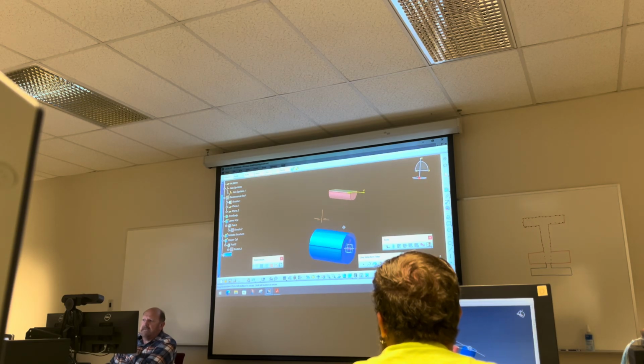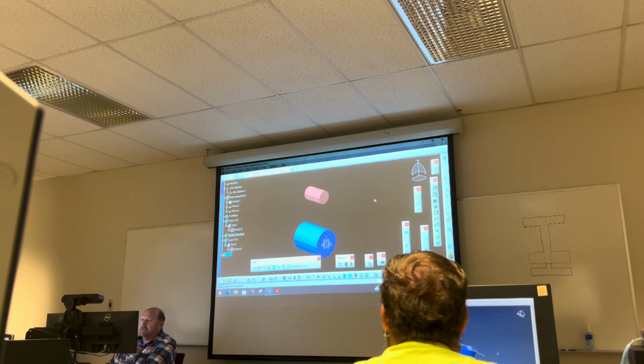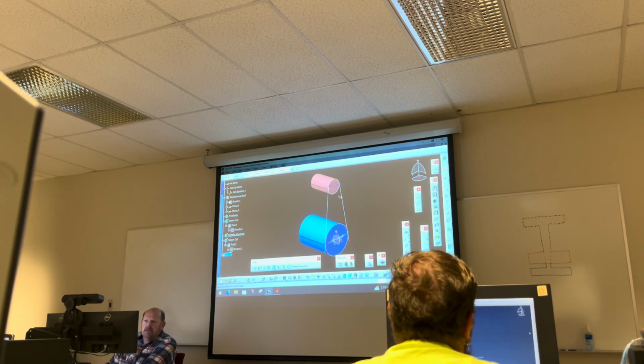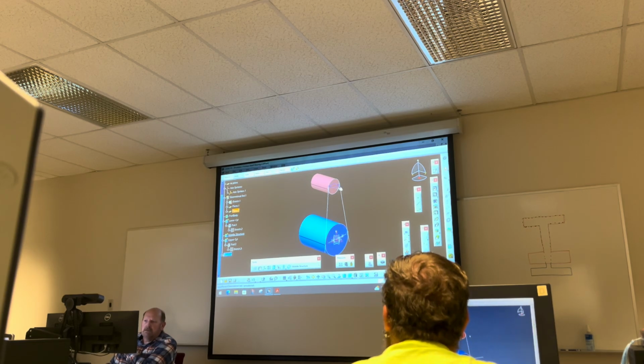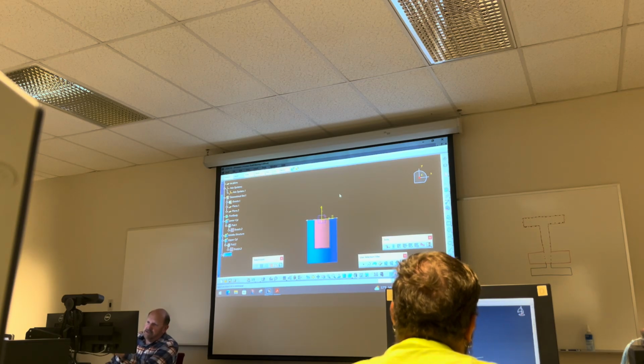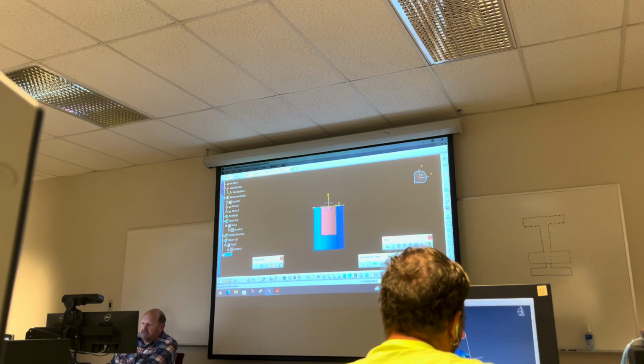So I build a plane, which is hidden. So there's my plane, right? And all I did was I'm going to build a sketch on that plane. Okay. So I'm still in this object. I'm going to pick that. It's going to put me right on. You're looking. The reason you don't see it cut in half is because I'm on that plane right now. But obviously, if I go like this, I can split apart exactly where the plane is.